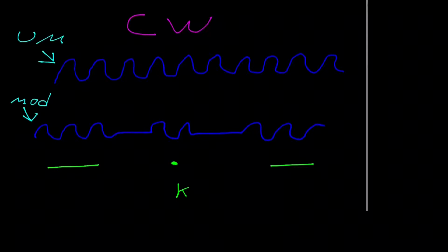It's turned on for a period of time, which is this big dash down here, and turned back on for a shorter period of time, which is this period here, then turned off for another segment of time, and then turned back on. So this is a da, dit, and da, and this is actually the letter K. This is, again, CW modulation, one of the simplest forms of modulation, by turning the carrier either on or off at specified time frames.